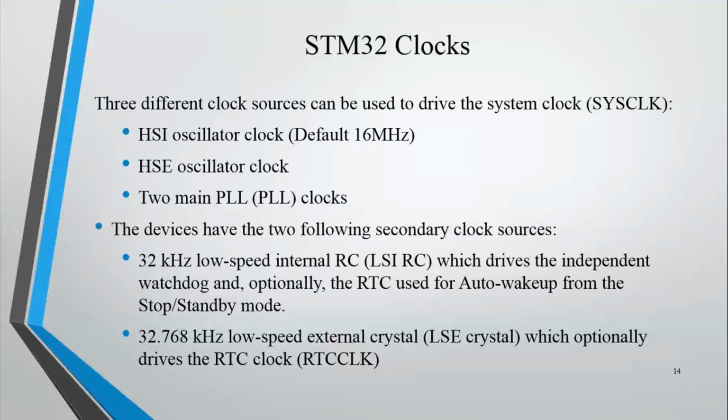If you have a standalone device without Wi-Fi and other things for syncing the actual time, what will be there? Inside this controller, there is a particular peripheral known as RTC, real-time clock. If you configure this, you can configure the actual time of the controller, and based on the time, you can perform certain actions. Say a device controller, when a device should be on at a particular time, where will you configure that time? In RTC. So the two secondary clock sources are generally used for RTC.